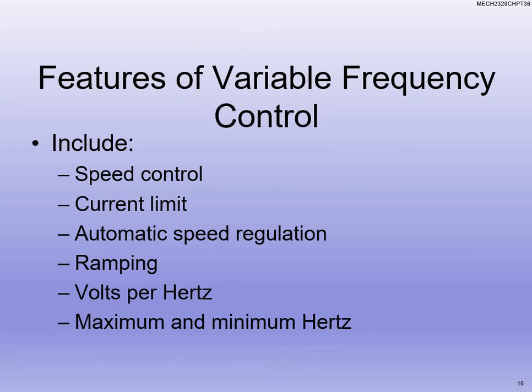So what's the point of using a VFD, a variable frequency drive? Speed control. That's the biggest thing. We can dial down. We can change the frequency, and changing the frequency slows the motor down. Remember, there are two methods of changing speed: increasing the number of poles, where we have the consequent pole motors, or we use VFDs, where we change the frequency. That also gives us speed control, so we can reduce speed if we need to.